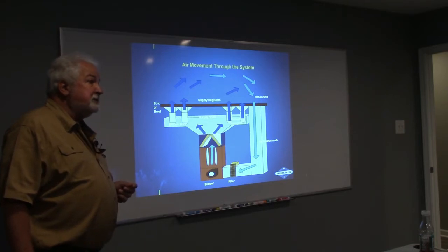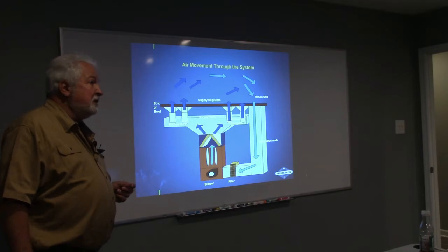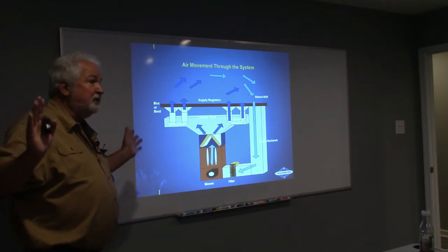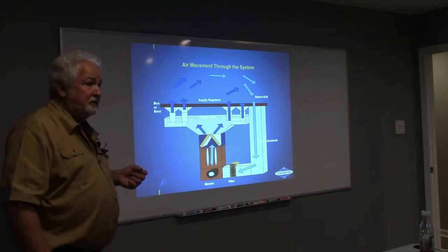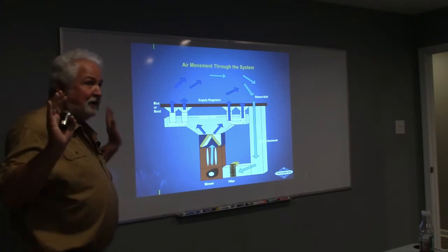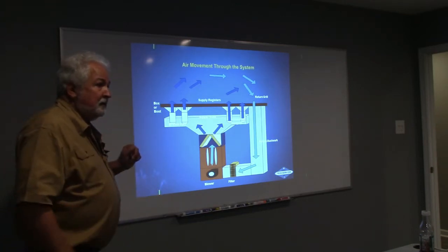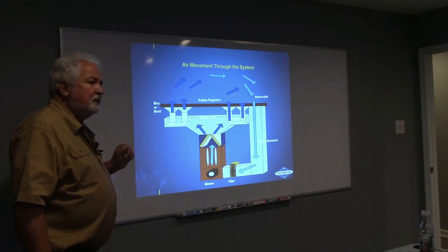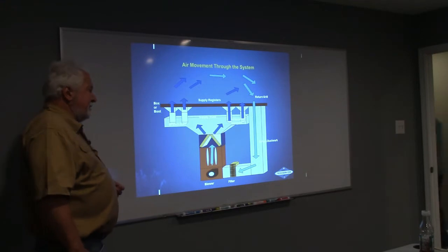It depends on how much velocity is really taking place, and I've seen a whole entire duct system change where the customer is completely satisfied when I just rotated the damper 90 degrees. Yeah, I've seen it done. Now everything's great. Before, they hated it, but just rotating it 90 degrees fixed everything. Normally, the way your airflow goes is the way you put your damper, right? And I'll cover that, absolutely, it will.